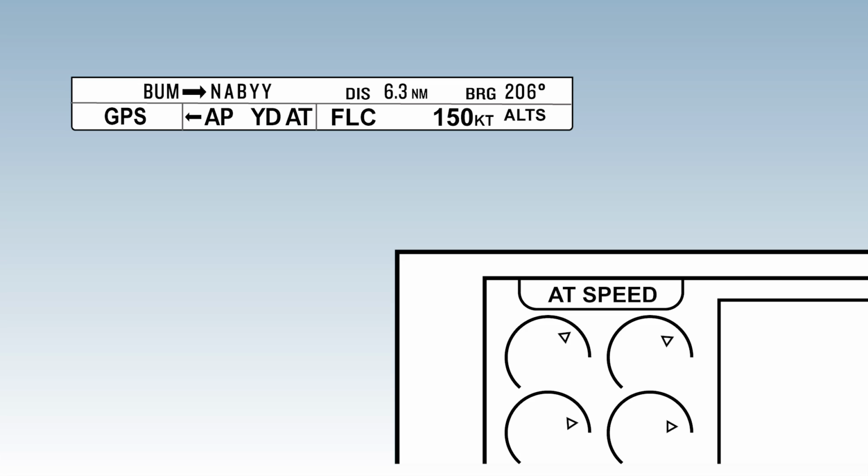During our multi-engine training, we spend the most time preparing for the event of an engine failure. Let's discuss how the autothrottle will respond during this critical phase of flight. The autothrottle detects an engine failure as a torque difference of 1,000 foot-pounds between the engines. If an engine fails while the autothrottle is engaged, it will either disconnect or park the throttle of the failed engine, depending on whether the failure occurs on takeoff or in flight.